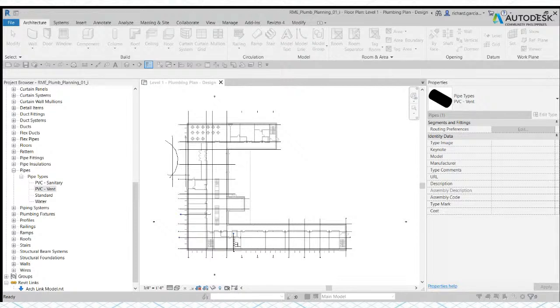And then for the preferred junction type, I'll just use T, because there is also another option here, which is tap. But in our case, I'll just use T. And then you can specify again the minimum size and then the max size junction. Let's change that one. So currently it's sanitary, so I'll just change that to vent. This one, T vent. And then for the cross, okay, what do we got here? So we have a sanitary again, so just change that one to vent.